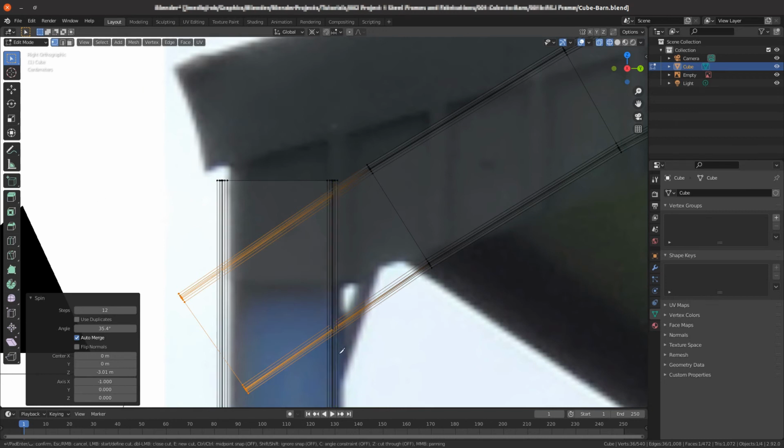It snaps to edges, and there's a few markers at the very bottom of the screen that show you what the knife tool does, and we want to cut through everything. So if you press Z, cut through becomes activated while the knife is in operation.